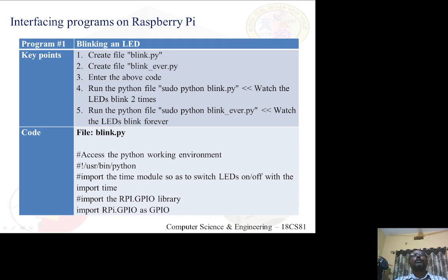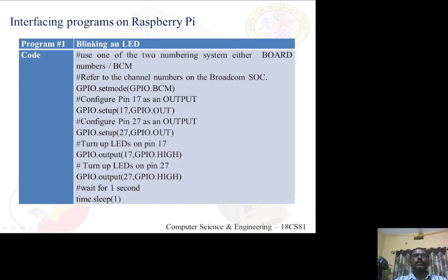So what I said first, the Raspberry Pi computer sends output through GPIO 17 and 27. This output is nothing but an input to the LEDs. So first, I need to configure these two pins as output pins. For that, just have a look at the code fragment here.